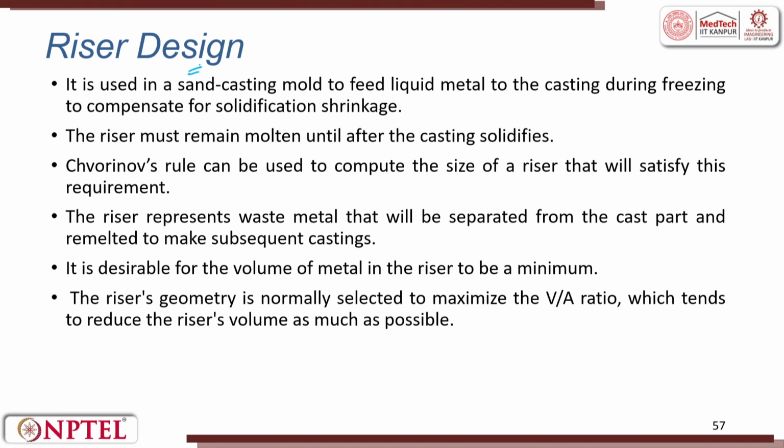Now, let us look into the riser. It is used in sand casting mold to feed liquid metal to the casting during freezing to compensate for solidification shrinkage. The riser must remain molten until after the casting solidifies. Chvorinov's rule can be used to compute the size of the riser that will satisfy the requirement, V by A ratio. See, if it is a straightforward cylinder, V by A is good. But if you have a complex shape, then this becomes a little difficult.